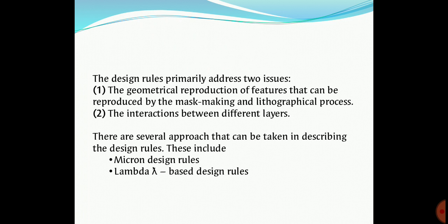In the micron based rules, dimensions are stated in micron resolution, and they are normally used by industries. The lambda based design rules were popularized by Mead and Conway, and every single parameter is expressed in terms of lambda. They are used in the educational context and in the design of multiple project chips.